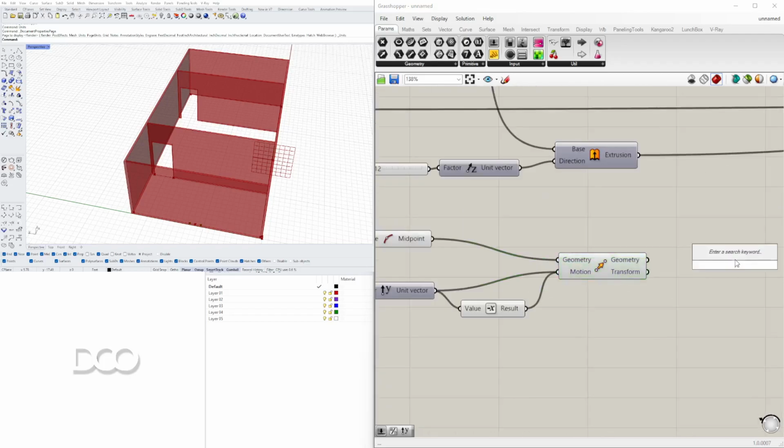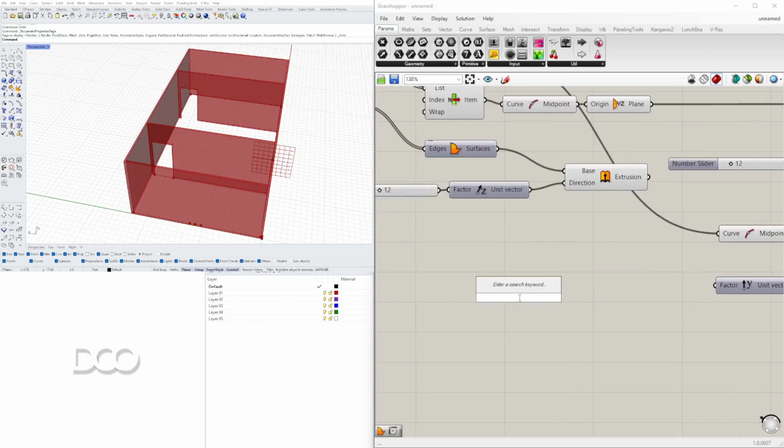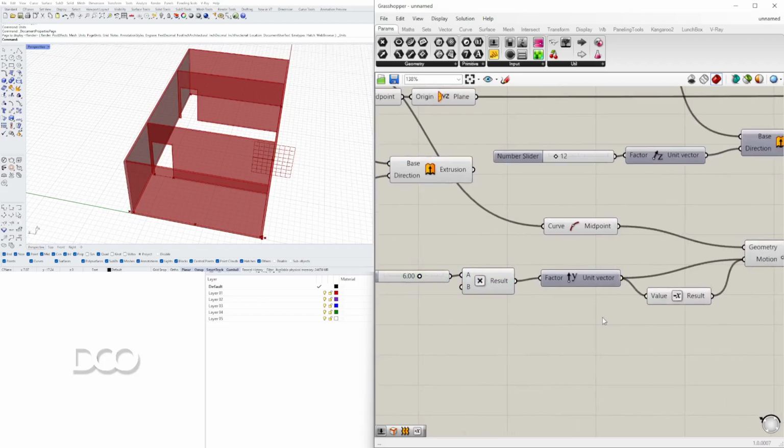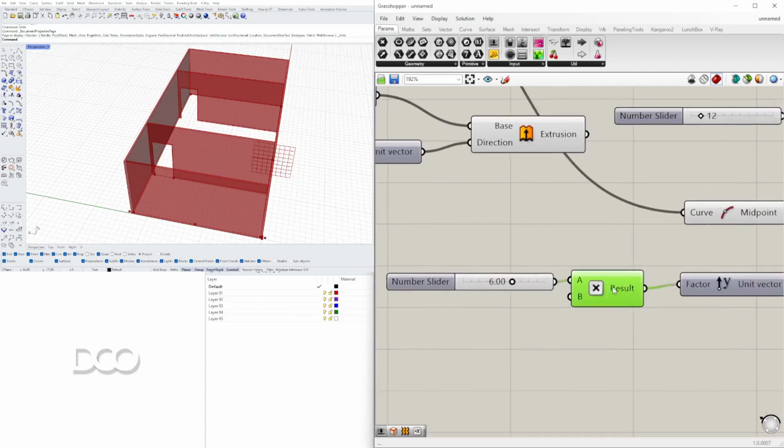Now I can create a polyline here on the vertices. Here, now we can pick a size of the window. So if I want it to be a 6 foot, so I'll do 6.00, and I'll actually divide that by 2 because it's going to do 6 feet this way and 6 feet this way, and that would actually be 12. We want it to do 3 and 3, giving us the overall size that we are looking for. I did times 2, so it's actually divide by 2.